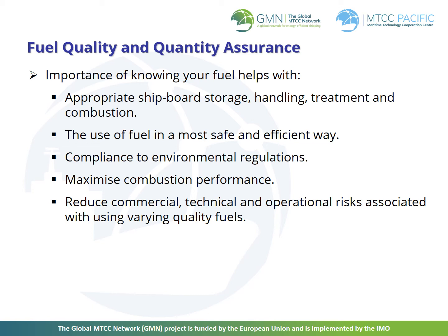Using better quality fuel and/or a higher grade of fuel can lead to improvements in energy efficiency, safety of combustion systems, and/or prevent degradation. Furthermore, this will help to meet the regulatory requirements to reduce the sulfur level in bunker fuel. More and more refining processes and also blend components are being used, which could result in an increase in the levels of highly abrasive particles of aluminium and silicon, or affect a fuel's chemical stability over the long term. This has also raised concerns about the ignition and combustion quality of fuels, along with issues related to the stability and compatibility of the fuels.